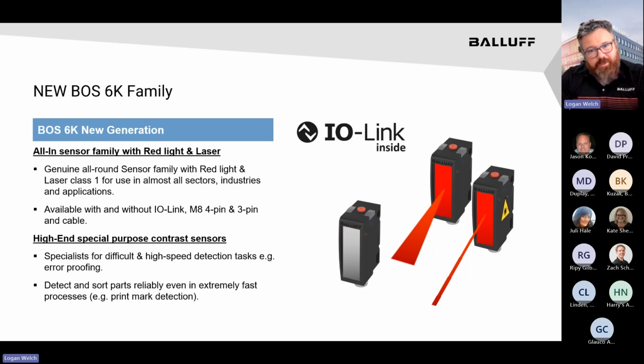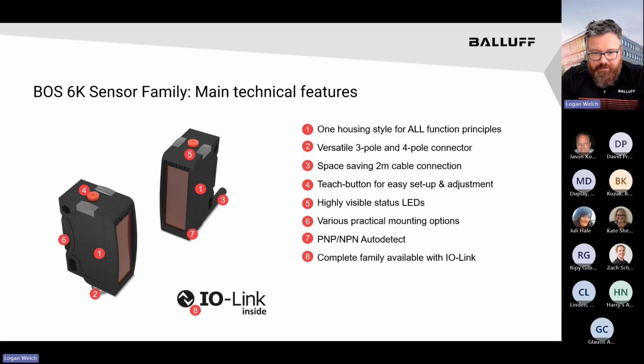So something else to think about for your application is, do you need extra data? Do you need a network-based hub? These are compatible with them. We're not going to dig into this too much. I showed you it up close on the camera, but there's a push to teach button on this family. That's becoming more common in photoelectric sensors. We're seeing that in a lot of different families, not only internally to Balluff, but competitors. Push to teach is a much easier way to set up a background suppression sensor than maybe a potentiometer on top. So this does have a push to teach. It has a power and an output on/off light.